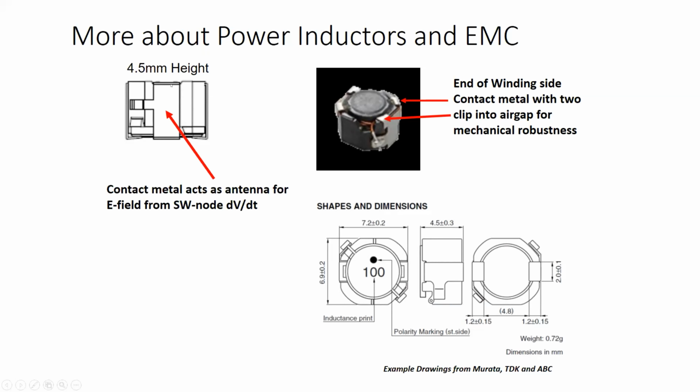Very good is relative, right? When we're talking about, is it ideal for the frequency we're trying to transmit? Maybe not. But even if it's not tuned to that specific frequency, it still can become an antenna. We're still applying that time varying signal to it. So we have to be very careful with how we do this, even when the start of winding is to the switch node in this particular case. And that is the way it should be for this particular inductor.